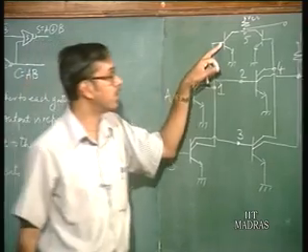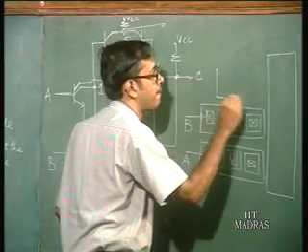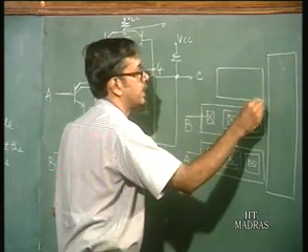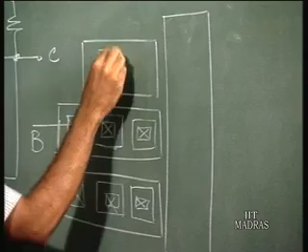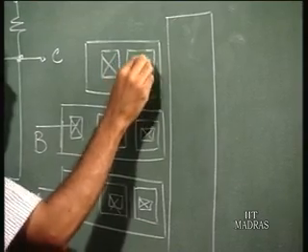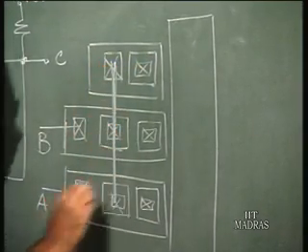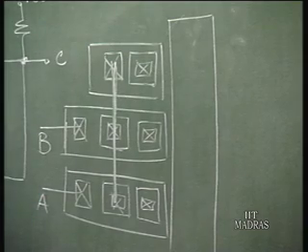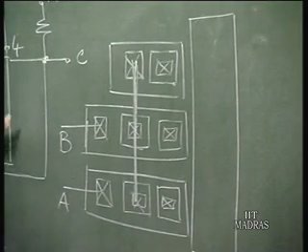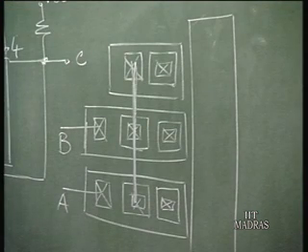That particular transistor has just one collector. So, you draw the base like this and this is the collector. You short them. This is the metal line running, just short this up. This is how you make connections.